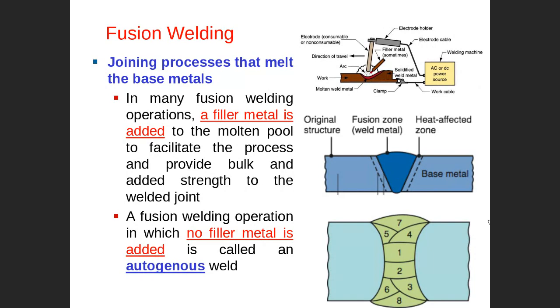How do we compensate for the evaporated material? You need to melt the filler material and drop liquid filler here to compensate for the material lost in evaporation.